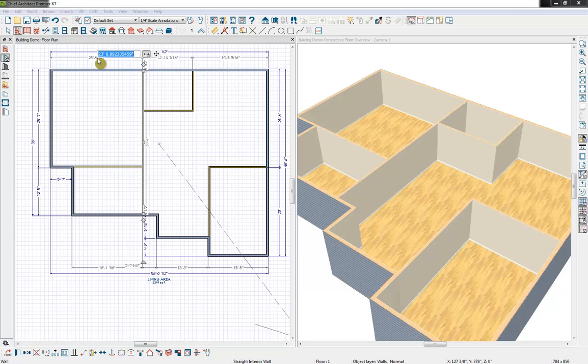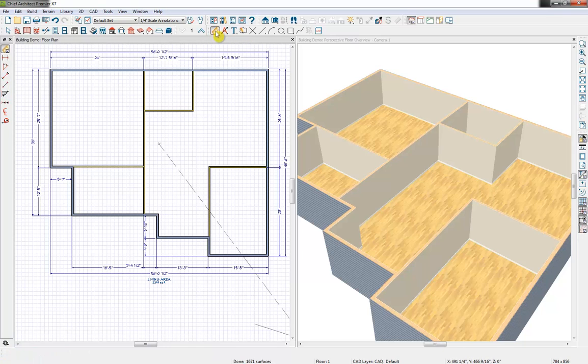So we'll click on this guy and let's move that to about 24 feet. And I've been using my automatic exterior dimensions. We also have more manual dimensions. So through this ruler, our dimensioning tool, I'm going to select our interior dimension tool. We do have many different options, so you can place the dimensions on here as you need for your own accuracy. And then I'll single click on that wall.